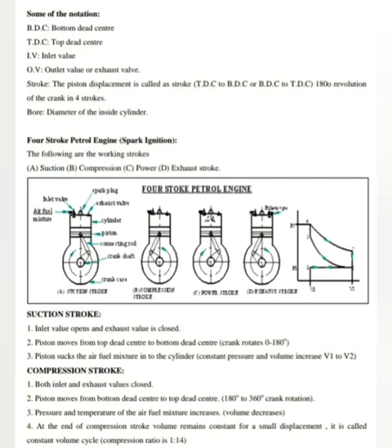When the piston reaches the BDC, the suction stroke ends and the inlet valve is closed. The suction of the air takes place at atmospheric pressure and is represented by the line 1 to 2 on the PV diagram. With this stroke, the crankshaft rotates through 180 degrees, or half a revolution of the crankshaft. The energy required for this piston movement is taken from the battery or from cranking the engine.